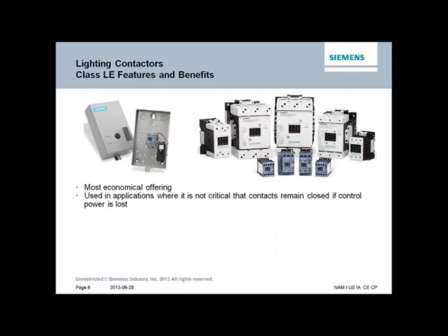The contacts are rated from 20 to 400 amps at 600 volts, and they come in 3 and 4 pole configurations. The 30 amp and the 60 amp contactors offer up to 12 pole configurations by using multiple 3 and 4 pole contactors all mounted on the same mounting plate with the coils daisy chained. Each individual contactor can have 3 or up to 4 poles only.